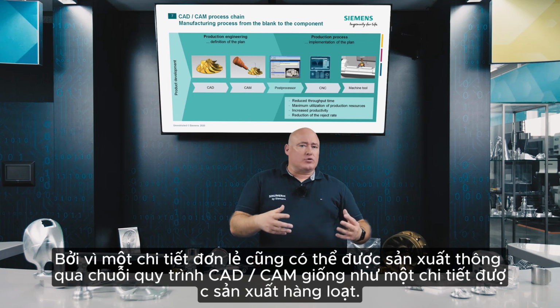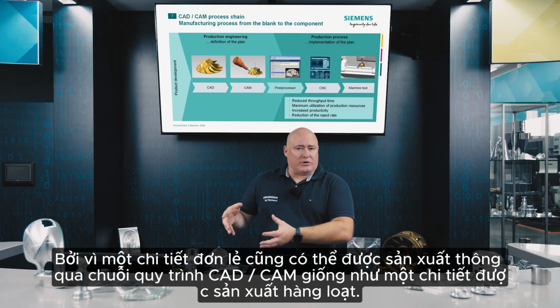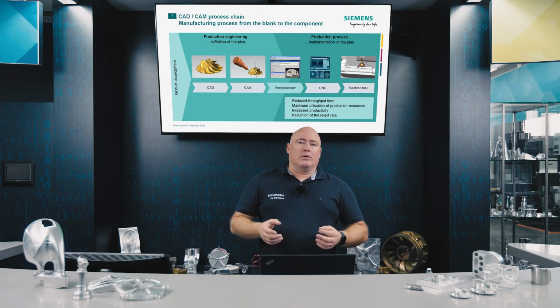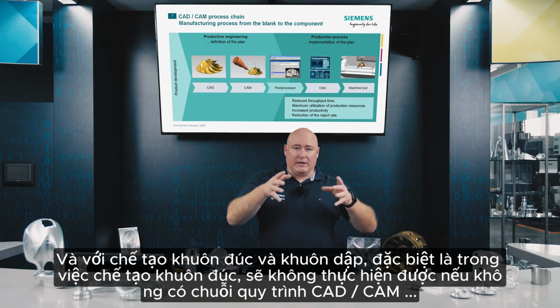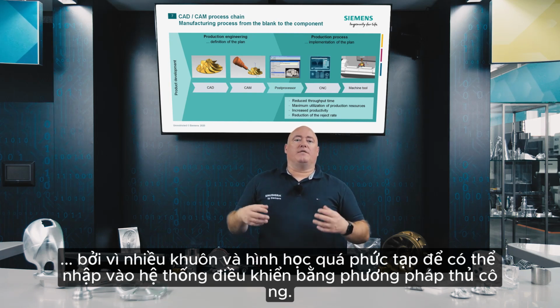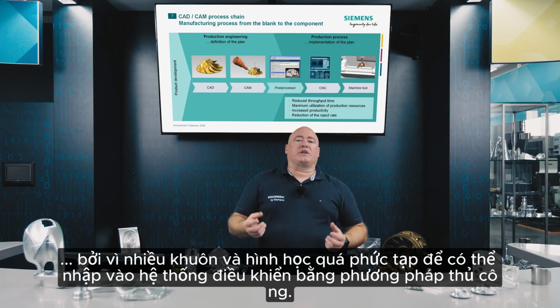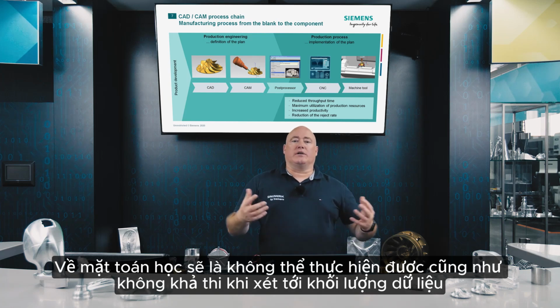Because a single part can be produced just as well via a CAD/CAM process chain as a component for mass production. And mold and die making, especially in mold making, just doesn't work without the CAD/CAM process chain, because many molds and geometries are too complicated to enter into the control system manually. It's mathematically impossible and not feasible in terms of the sheer volume of data.